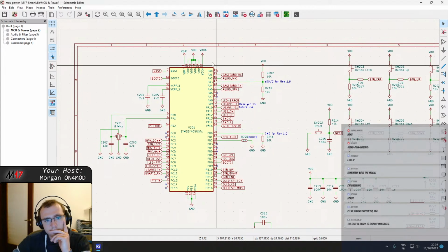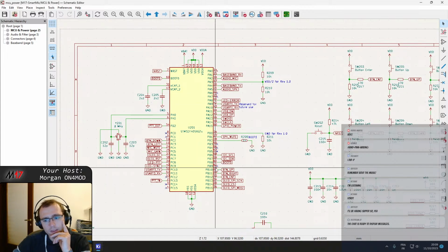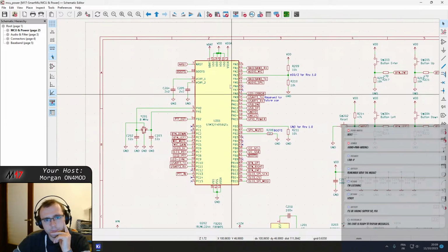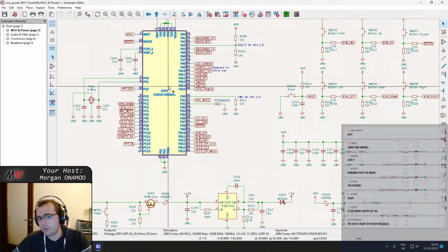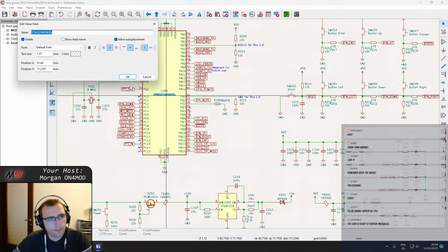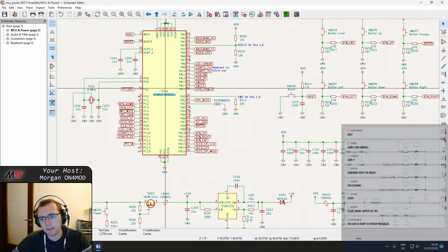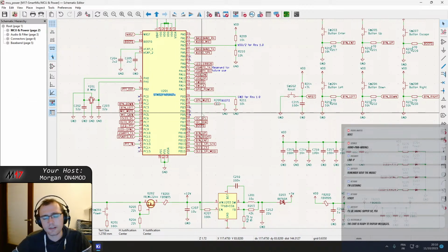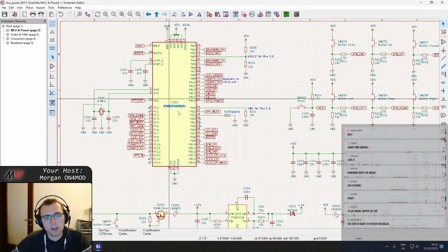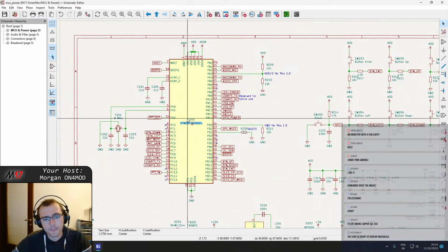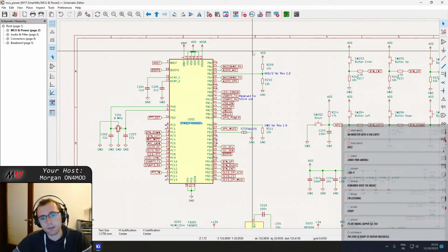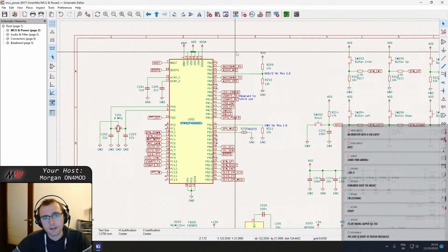So what we could actually do is filter the power supply to the MCU with ferrite beads. I don't know the maximum frequency of this one, but let's say it's in the tens of megahertz range, maybe a bit more. This might generate very high frequency noise on the voltage bus. So we could put a ferrite before it, so that the noise it generates doesn't propagate back to the rest of the system.